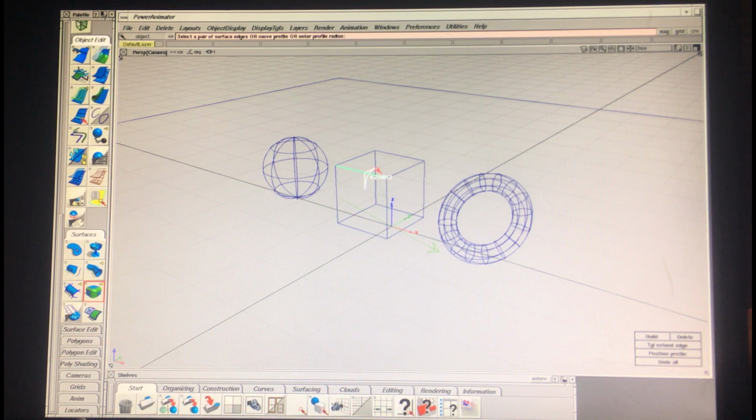It says it's looking across here, and it's going to take this whole bar here, and give it that profile. And you can see here, because I've clicked an edge, it added another one, which we want to do eventually, but we don't want to do that yet. So I'm going to click this, try not to click on one of the edges, and drag until it's about 0.2. And now that I have one set at 0.2, if I click on any other edge, it'll be the exact same number that I set here.